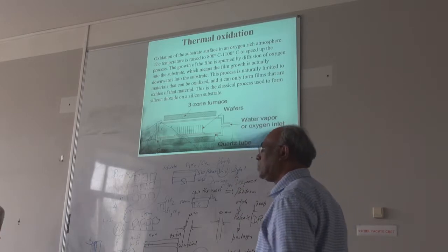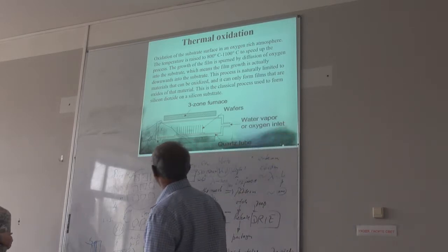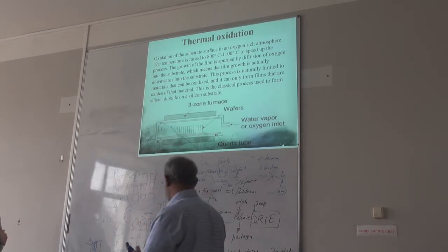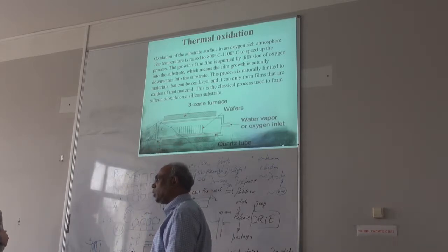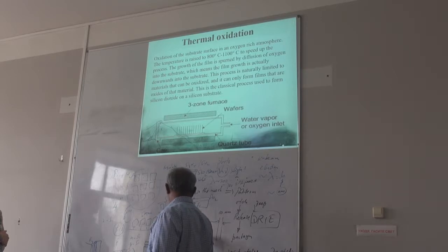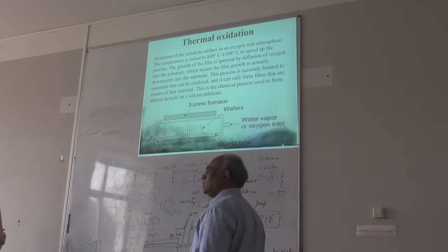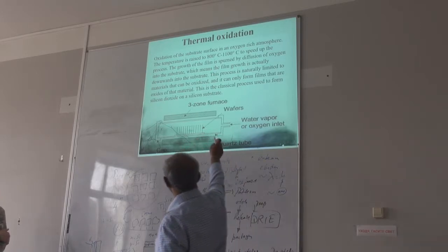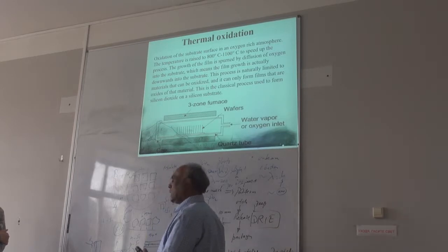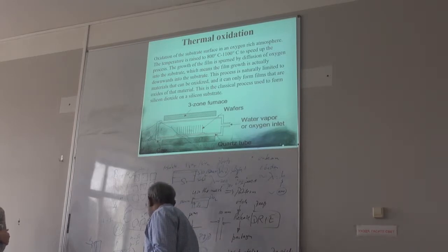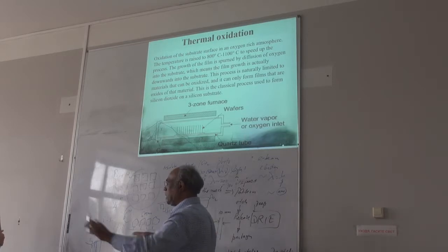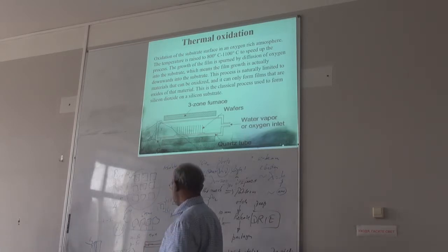And how do you control the temperature field inside the chamber? The furnace has a temperature controller, a PID controller, so you can keep the temperature quite stable. You have the set point, so you can set it to 1000 or 900 C. You wait until it comes to a stable temperature, and once it is stable, then we introduce the oxygen.